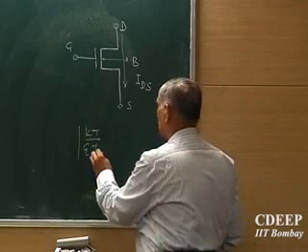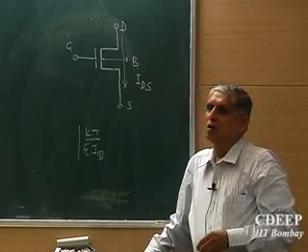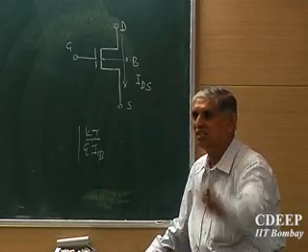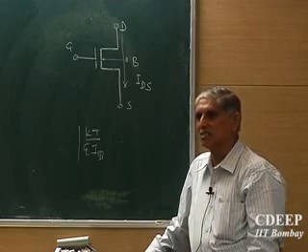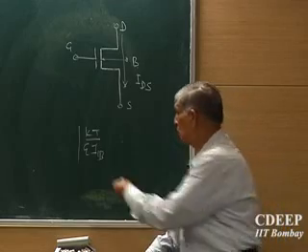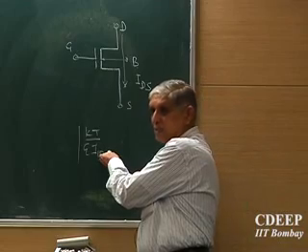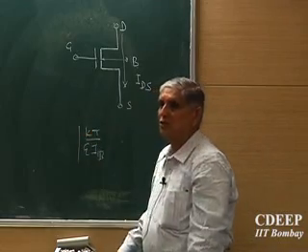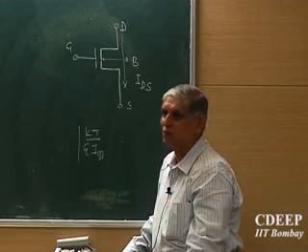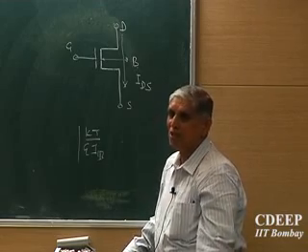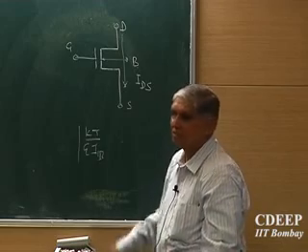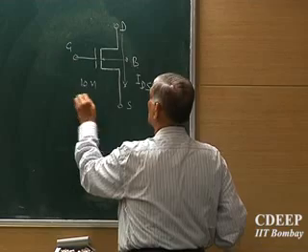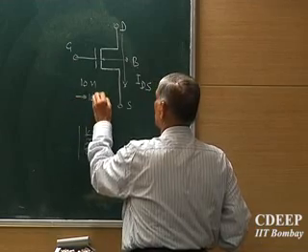Sorry, IB. So IB is the input current and that decides the input resistance. Is that clear? Even if it is microamps, tens of microamps, with 25 millivolts, this will be at least a few kilo ohms, 1 to 5 kilo ohms, not much more than that. Whereas in the MOS transistor, typically you may get 10 mega ohm, or better, maybe 100 mega ohm.